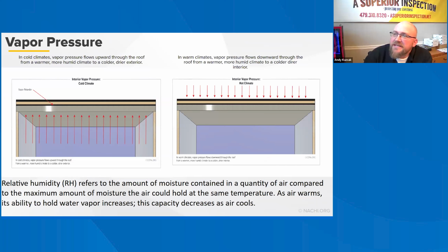All right, the laws of physics govern how moisture reacts within various temperature conditions. The study of the properties of moist air is technically referred to as psychrometrics. A psychrometric chart is used by professionals to determine at what temperature and moisture concentration water vapor begins to condense. This is called the dew point. By learning how to determine the dew point, you will better understand how to diagnose moisture problems in a house.